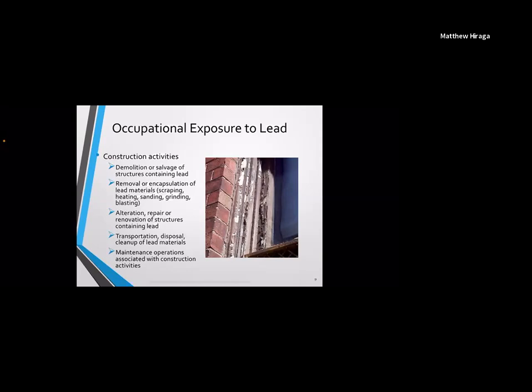Transportation. I can't throw it in the back of my buddy's Nissan hard body truck and he lets it bounce in the back on his way to the landfill. Disposal and cleanup of the contaminated materials, right? Not only the debris that you removed, it could be the plastic that you had dropped on the ground, critical barriers, gloves you were wearing, Tyvek suits you were wearing, all that kind of stuff, or even the lead waste that collects inside of the HEPA vac. You don't just leave it, right, for the next people.